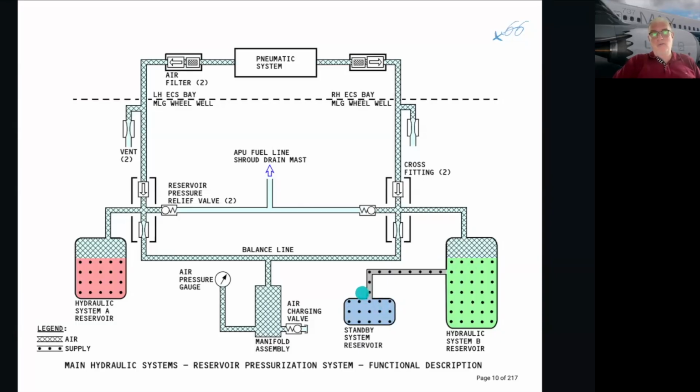We can also pre-charge through a service cart with nitrogen if we prefer to do so through this air charging valve on a manifold assembly. It's a normal Schrader valve.